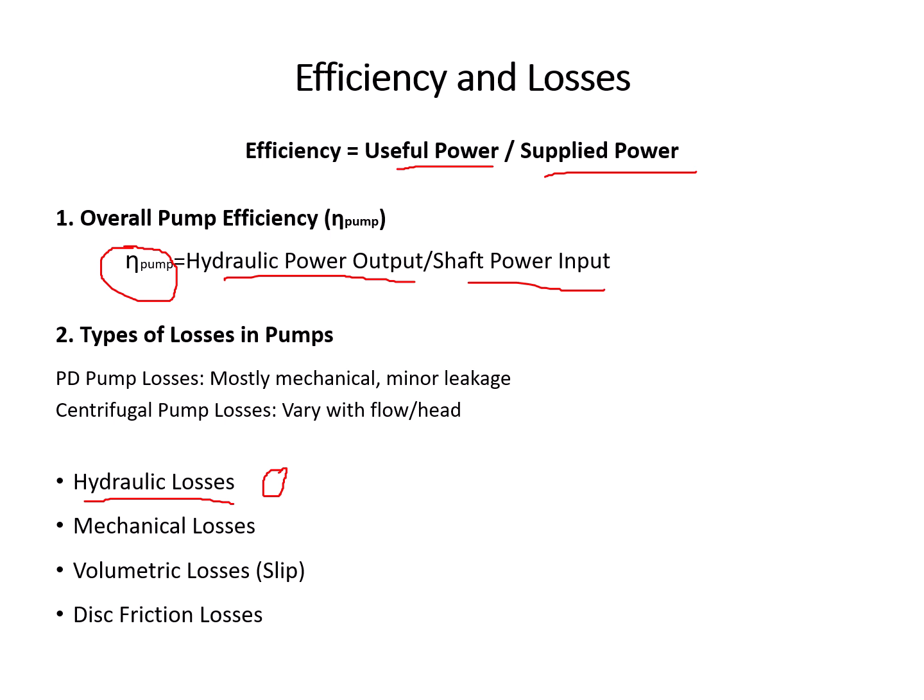It is inside the pump passages, the impeller, the volute, and so on. This is what causes the hydraulic losses, which lead to pressure drop and reduced output. Hydraulic losses increase with poor design of the pump itself, like sharp bends inside the pump, or a rough inner surface. This all leads to increasing the hydraulic losses.